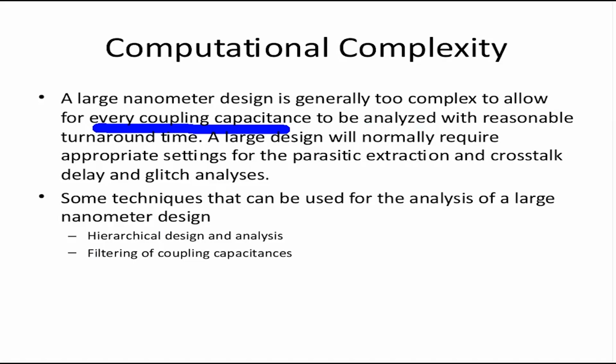So there are some settings to make this analysis more practical. So there are some techniques. One is the hierarchical design, the other is the filtering. What hierarchical design means is, let's say a chip has 20 individual functional blocks, and at the chip level these blocks are just stitched together. Synthesis also would need you to synthesize every block separately, because a full chip synthesis might not be a good idea, because again it will take a large amount of time, right? So usually what is done in industry is that all 20 blocks will be synthesized separately and then stitched at the top level.